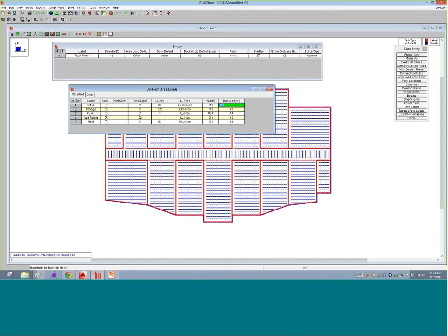You can attribute more to that dynamic mass. So what this is accounting for is superimposed dead load above and beyond the self-weight of the beams and the deck itself, and what we calculate for the seismic calculations. So we've got all that laid out.